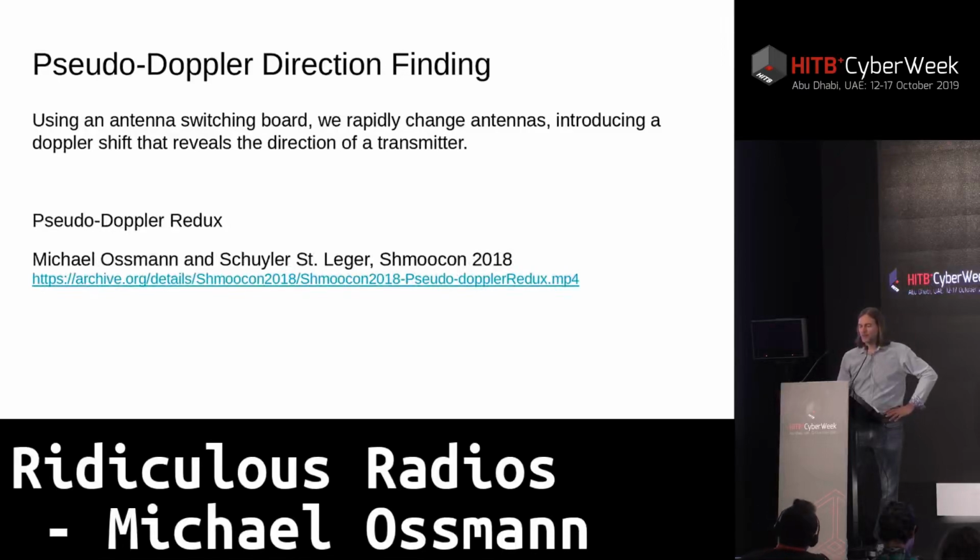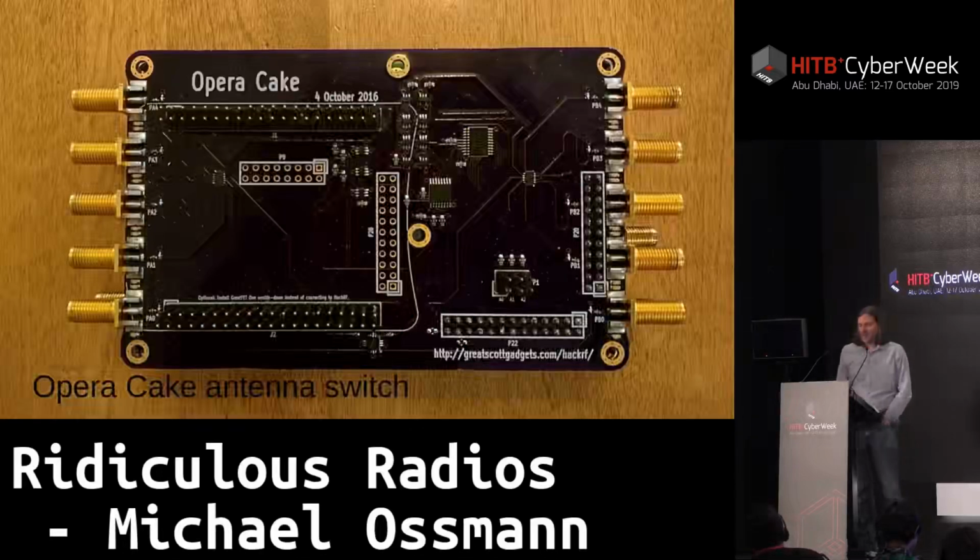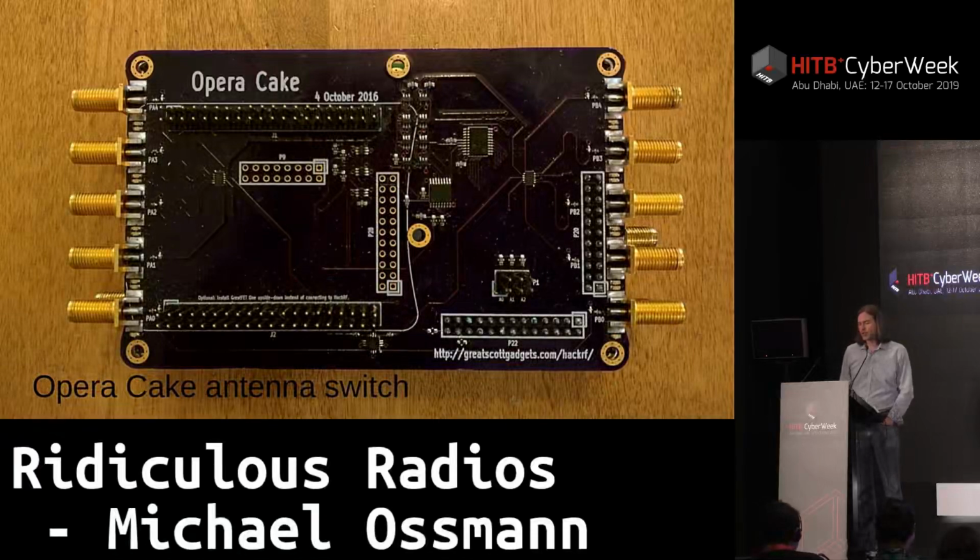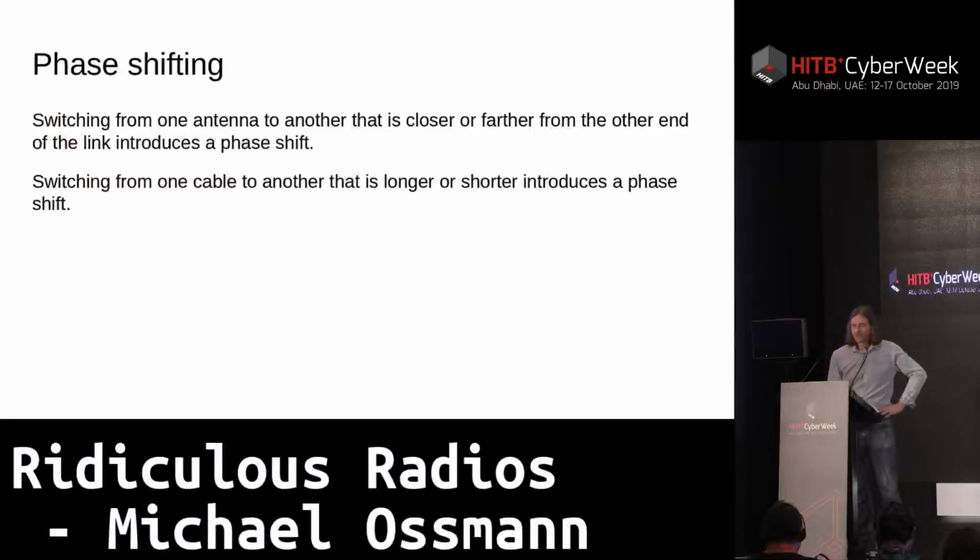Myself and Skylar gave a talk at ShmooCon in 2018 about implementing this technique on this board that I designed called Opera Cake. This is actually an add-on for HackRF, but it's an open source hardware design that is simply an antenna switch, or really an RF port switch. You don't have to use it for antennas. But in this case, we were plugging 4 antennas into this thing and then using the Opera Cake to switch rapidly between those antennas.